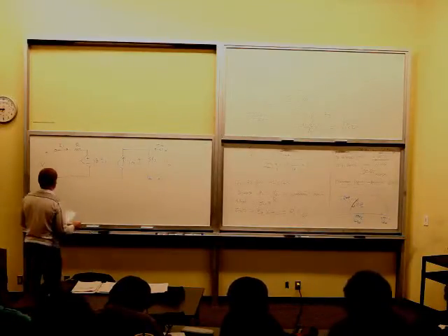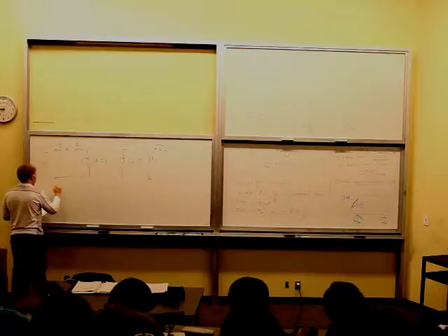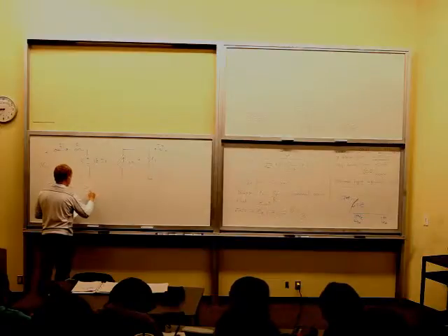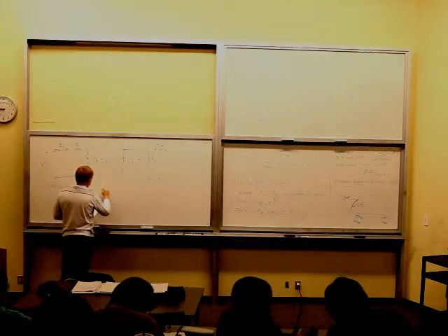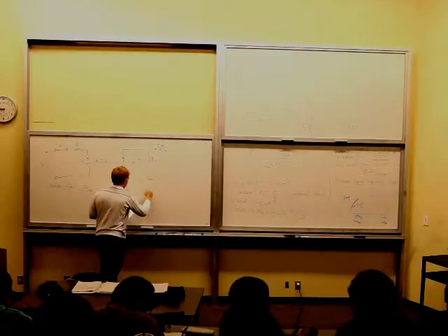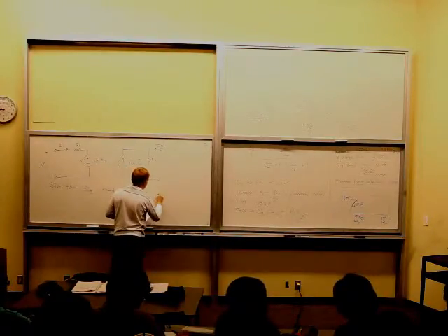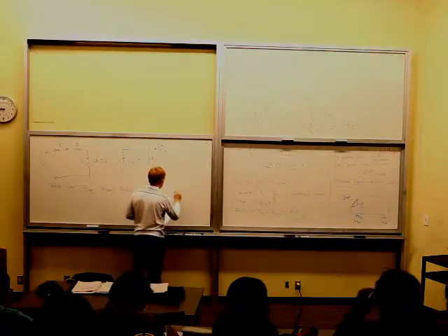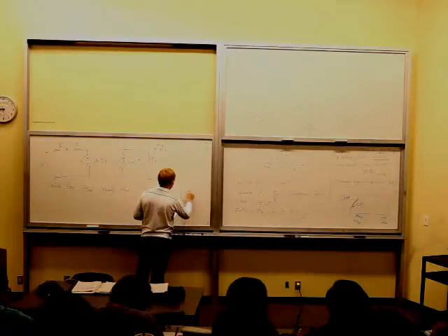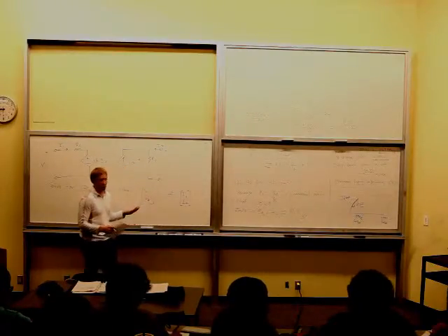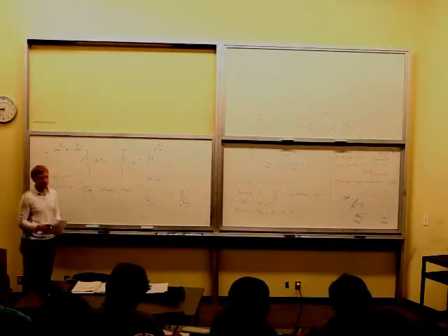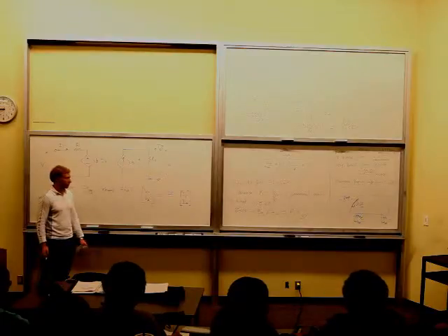So the question says, solve for the equivalent Z matrix. And then we explicitly say, recall that V1, V2 equals Z, so that's a big matrix, times I1, I2. So again, if you can't remember that, just pretend it's Ohm's law. So you just say V equals Z times I. It works just like Ohm's law. Same for conductance, you can say I equals Y times V.